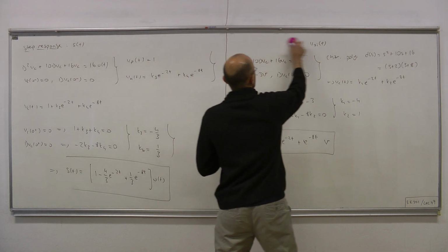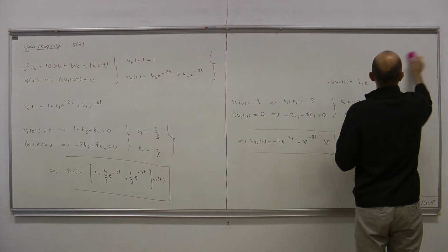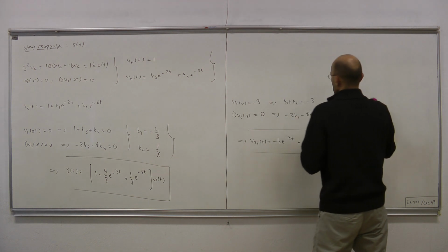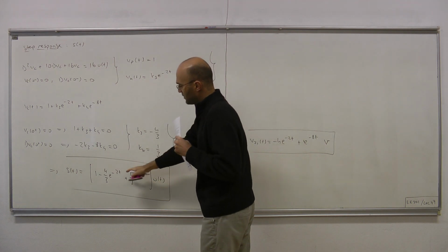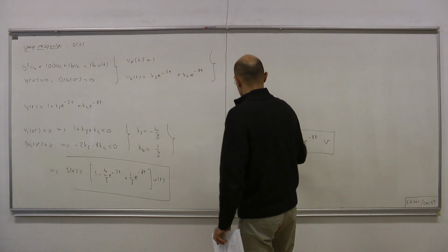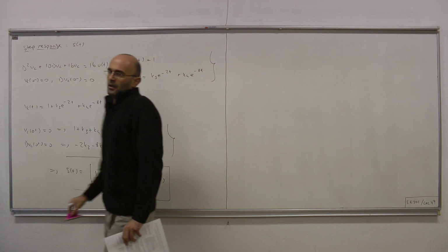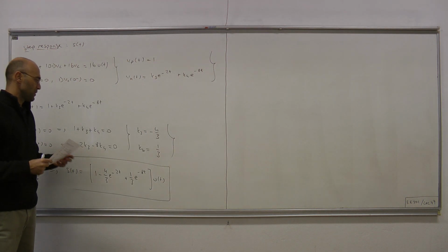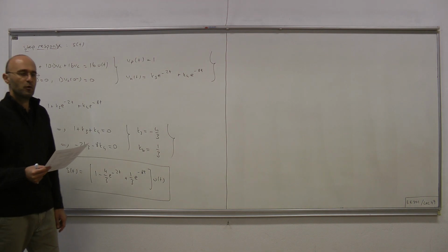Once we have step response, we can easily obtain the impulse response without looking at the circuit. All we have to do is, since the impulse function is the derivative of unit step, thanks to the fact that our circuit is LTI, the impulse response is the derivative of step response.